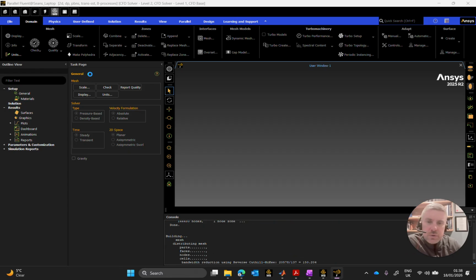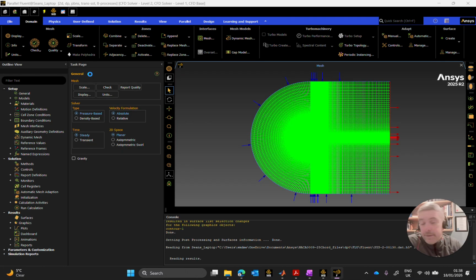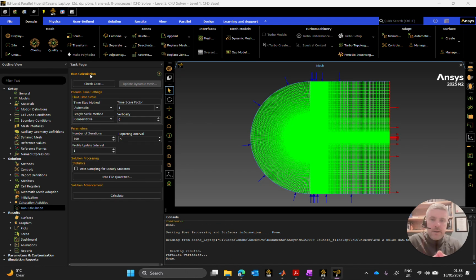What I was going to do was go straight into the grid convergence index method and mesh. And what I did then was I moved things into the report definition, because what I wanted to do was to try to automate some of the grid convergence index creation of metrics to evaluate what is broadly a statistical method.